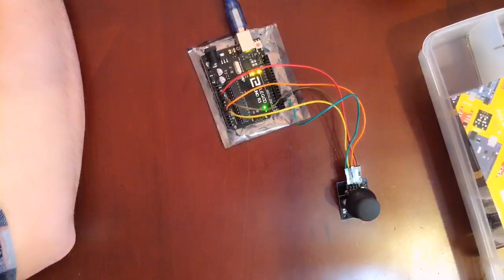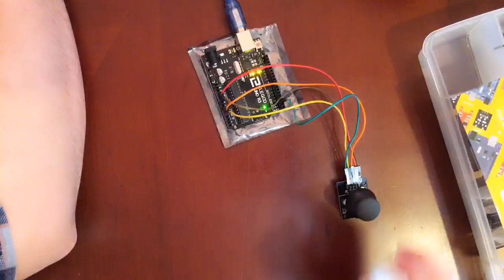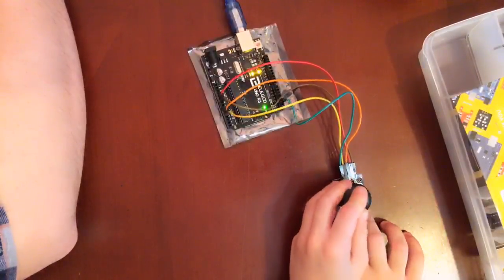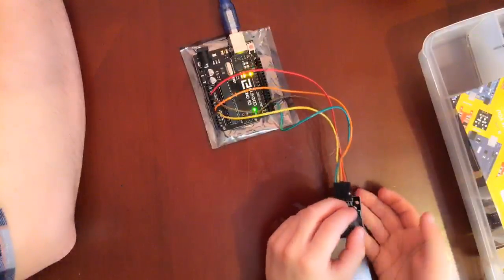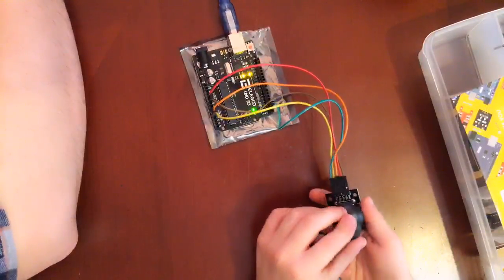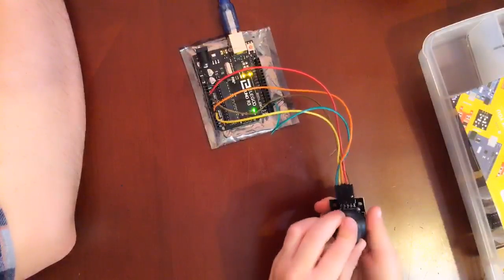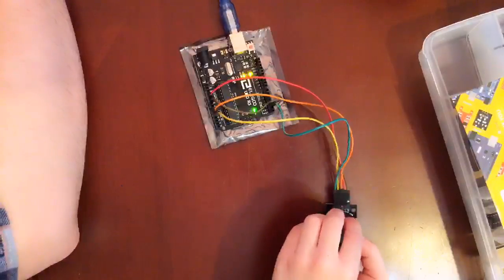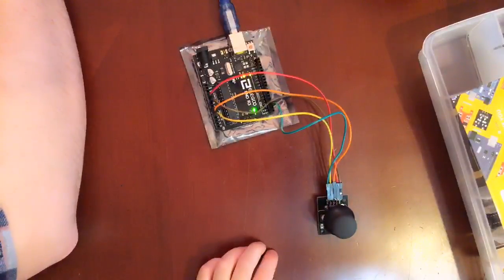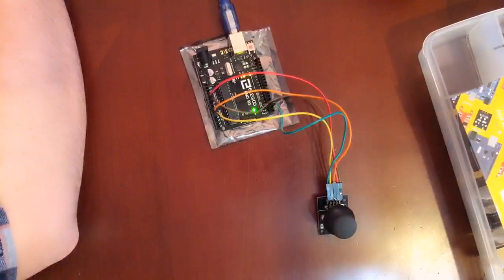Analog joysticks are basically potentiometers, so they return analog values. When the joystick is in the resting position or middle, it should return a value of about 512. The range of values goes from 0 to 1024. So all it's gonna do is show you that it's working, because we'll be able to open the monitor and you'll see the values for where the stick is pointing. Okay, so leave it right there, and it said it would show 512, right? Right.